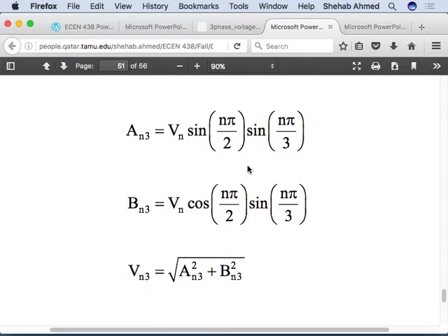Because if you have a voltage harmonic, it's a small value, but it happens to be at the exact resonant frequency of a circuit in your power system. And what's going to happen? You will excite that resonance. Right? Resonance means what? Resonance means it's an impedance that sees a harmonic at a specific frequency that it is tuned for, and at that frequency it becomes a very low impedance because the L and C cancel each other, and it's a small resistance in that case, so current will flow, huge current will flow.